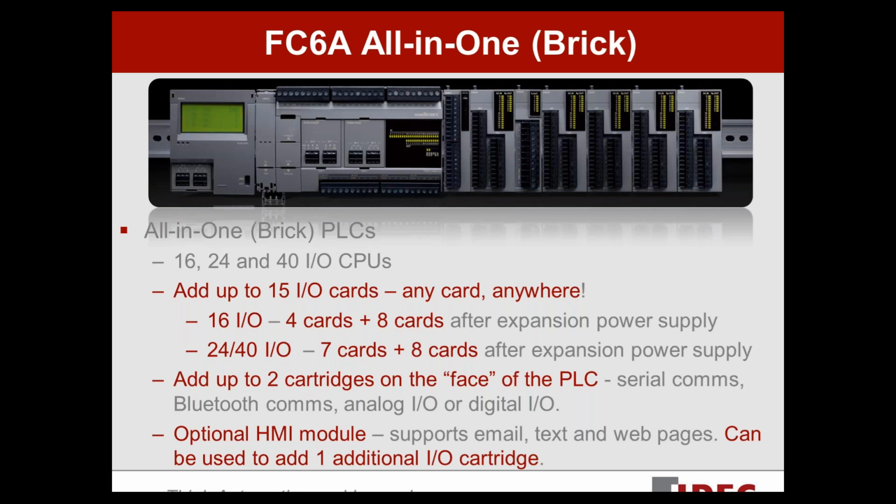And so the bricks are available in 16, 24, and 40 I/O, just on the CPU itself. You can add up to 15 I/O cards, and you can put any card anywhere. For those of you who have used our FC4A, FC5A PLCs in the past, you'll remember that the analog cards in those PLCs had to go in the first 7 positions, or first 7 slots, if you will. With the FC6A series, that limitation is no longer applicable. You can put any card anywhere.